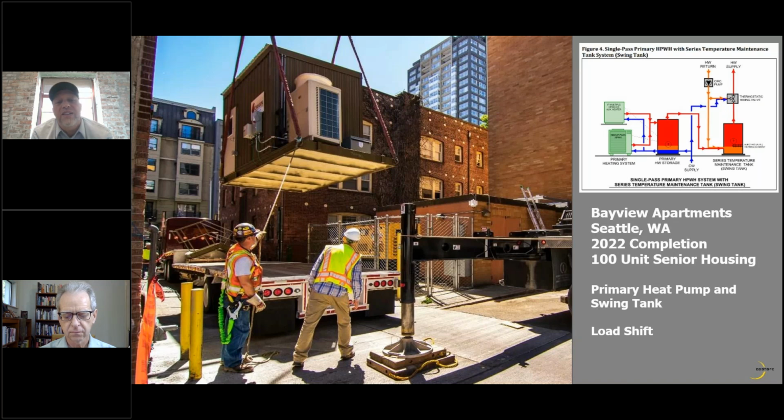They also are really nice because you can keep the occupants' hot water supply up. This particular project shows a skid built system using a Mitsubishi, and this is serving 100 unit apartments. And this switchover was done in 4 hours. We did this overnight. This is the importance of having the skidded out equipment, because you can do these swaps overnight with a little bit of planning up front. This is an exciting project. We've been metering lots of experiments looking at load shift with this one. So a lot of stuff on this.